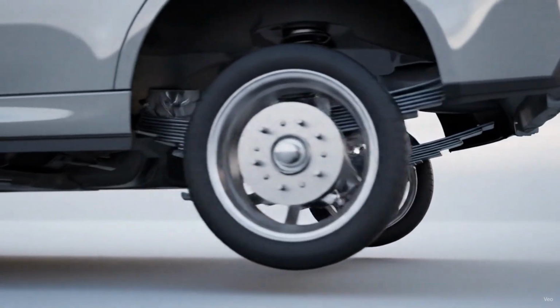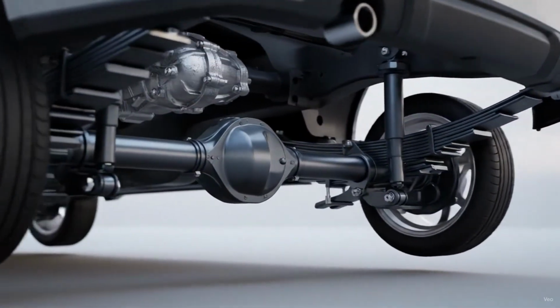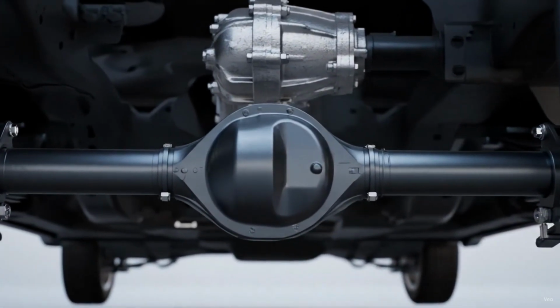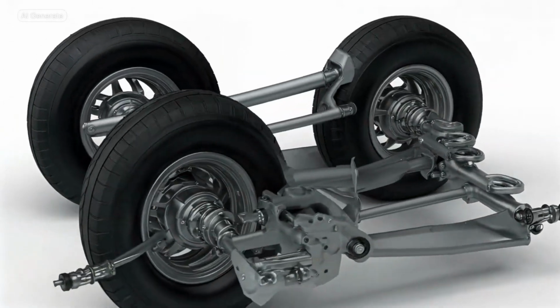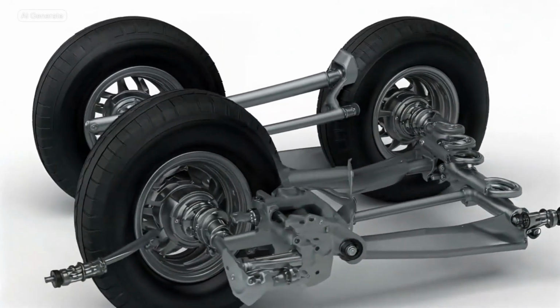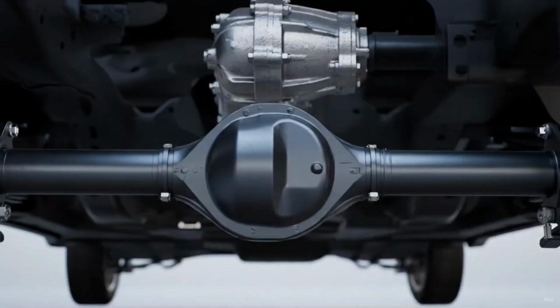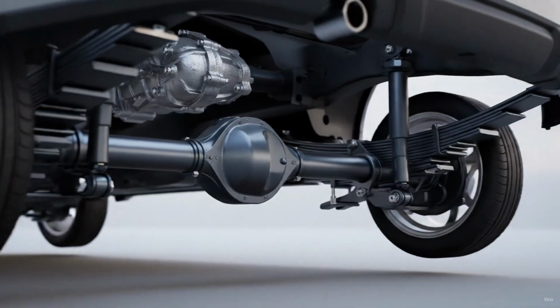Control arms, trailing arms, link arms. Location: multiple arms, at least two, often four for a four-link setup, connecting the solid axle to the vehicle's chassis. In the diagram, there are blue arms extending forward and slightly upward from the axle. Function: control arms are fundamental in locating the solid axle longitudinally, front to back, and sometimes laterally.